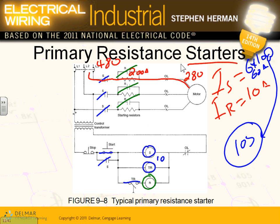What happens if you put a conductor across a resistor? You shunt it. So now the current is going to go right here, back here, and your 480 here will translate to what? 480 here. So they call it voltage reduction. You reduce the inrush by reducing the voltage.